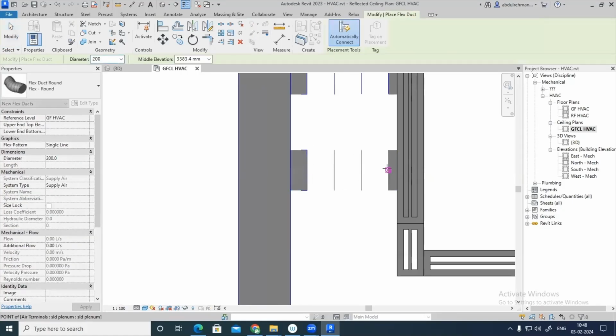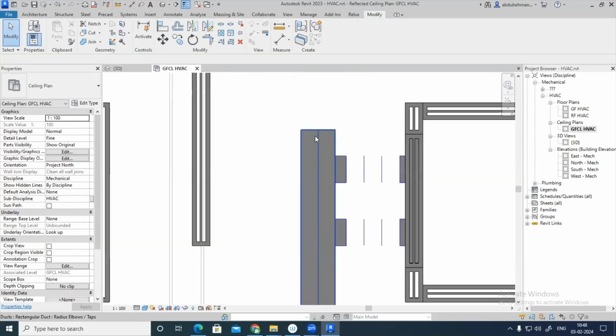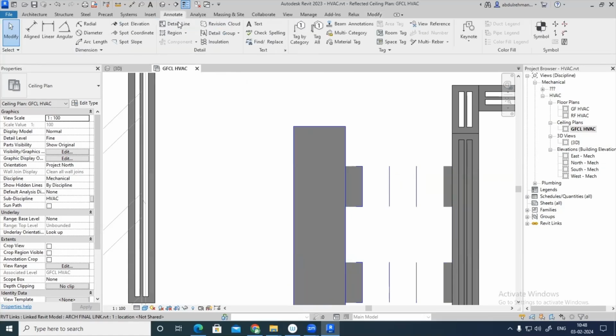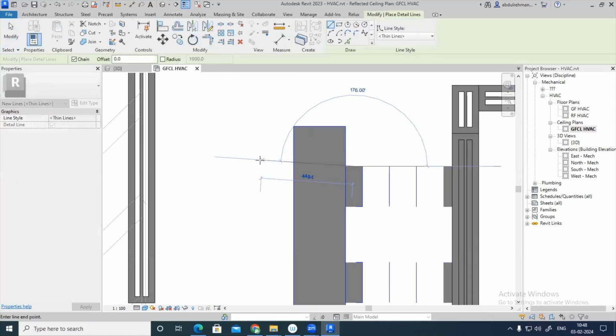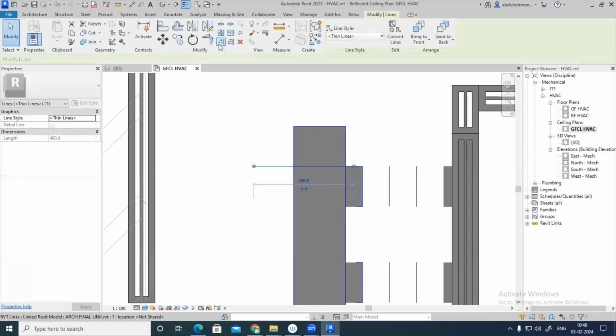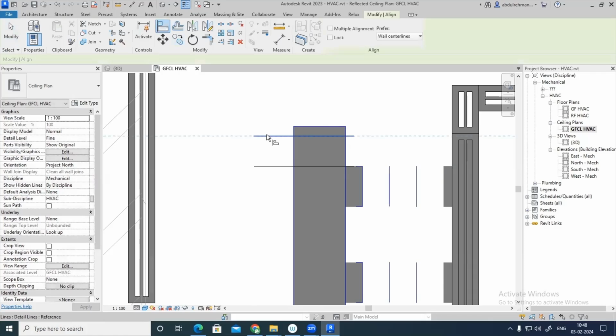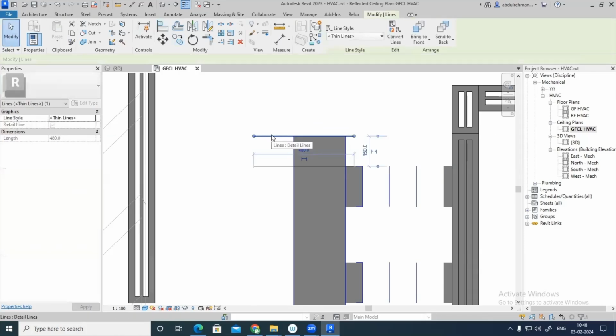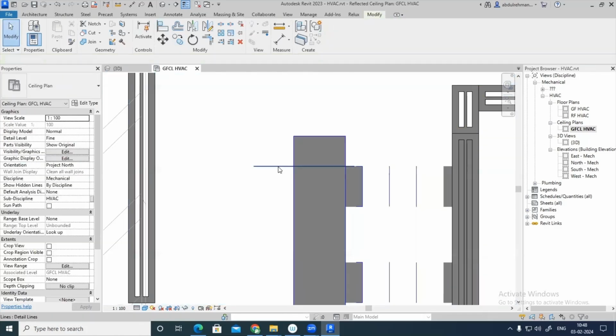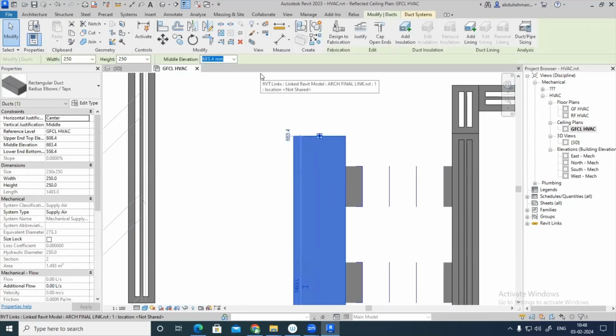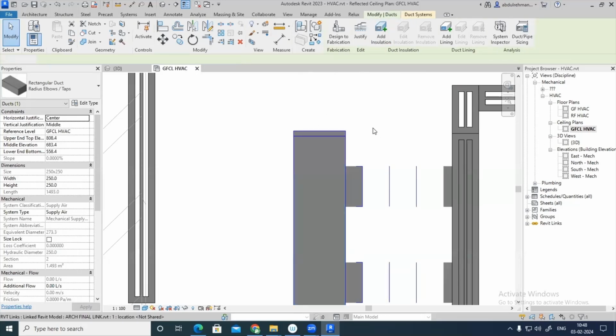Draw flexible duct we can. Okay. After the collar, we can extend this into 150 mm. Now we can align the duct until this point. See, please watch the drafting class before doing it. This AutoCAD cap open, and I'm just capping it. Okay.